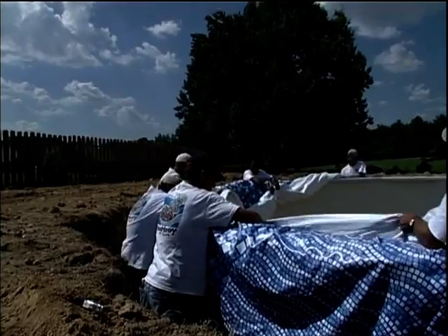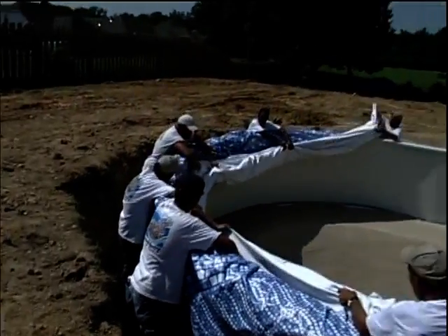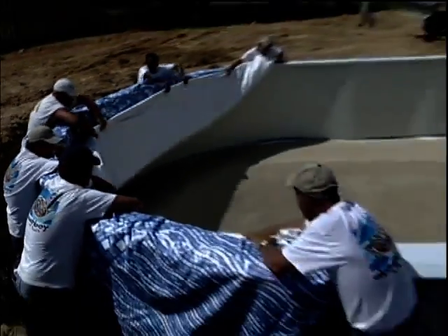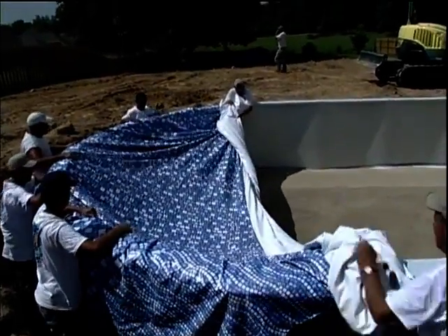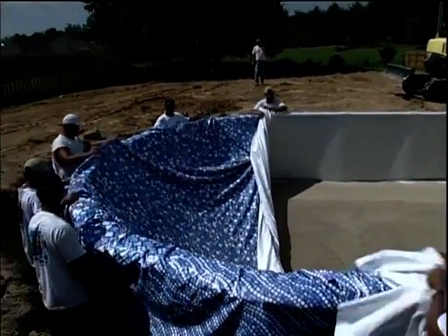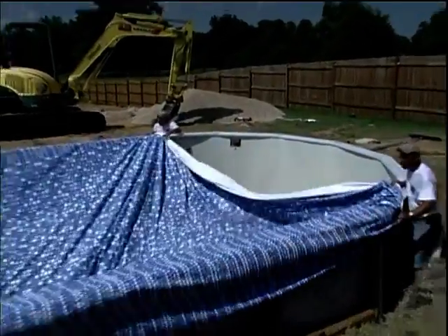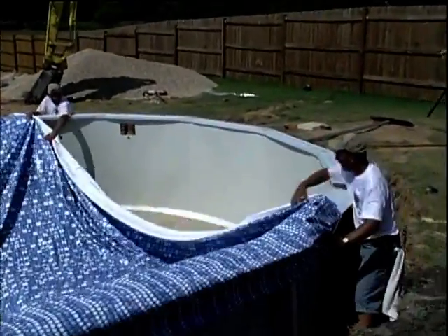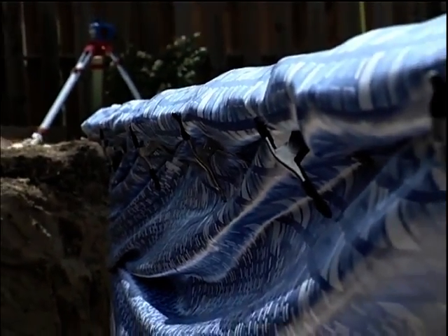The 2 end men will start to stretch out the liner, and when they give the command, the other members will throw the folded liner towards the center. The 2 end men will snap the liner forward toward the other end. Then they will unroll the liner until it is completely unfolded. At this point, clip the liner to the top rail using the spring clips around the entire perimeter of the pool.